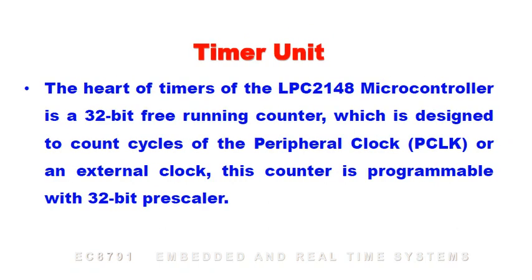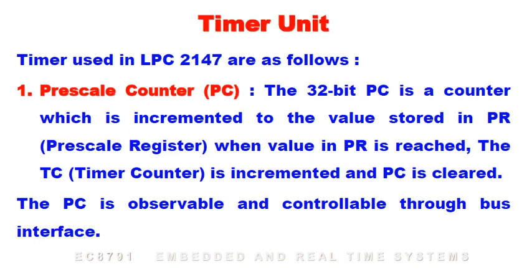The heart of the timer of the LPC2148 microcontroller is a 32-bit free running counter which is designed to count cycles of the peripheral clock PCLK or an external clock. This counter is programmable with a 32-bit prescaler. The timer registers used in LPC2148 are as follows.